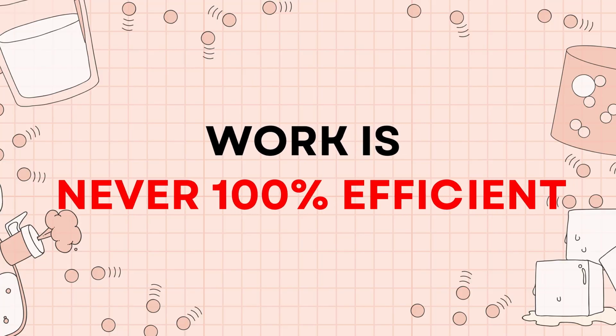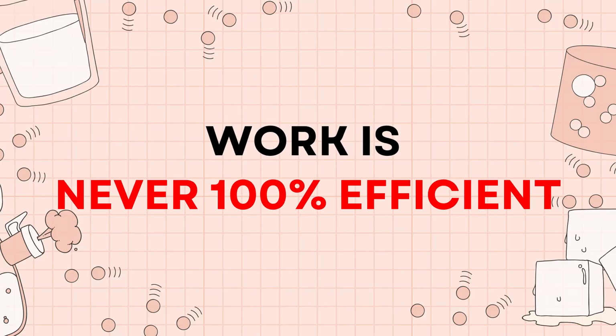When you leave the refrigerator door open, the heat it removes from the air near the door is simply pushed back into the room on the other side of the refrigerator and then flows back into the area being cooled outside the open door. This means that while the distribution of heat in the room changes, the room as a whole will not get any cooler. In fact, if you leave the door open for more than a very brief moment, the room will actually get warmer overall.